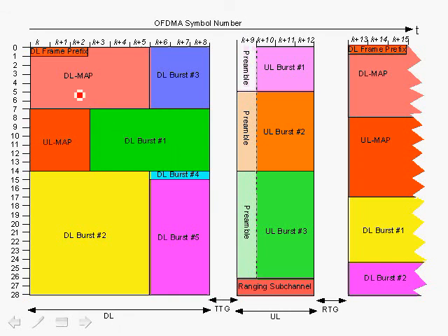As we mentioned, when you have a TDD frame, the base station sends the downlink, and in the downlink there is the specification for the uplink map, so that when the subscriber stations decode this, they can extract the uplink map, and from that they would know what the ranging subchannel is that they will use in order to do ranging and send ranging information.